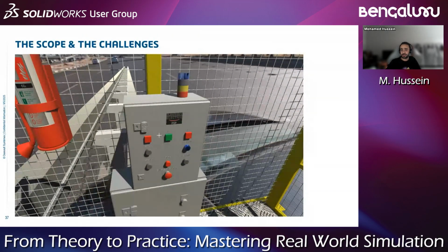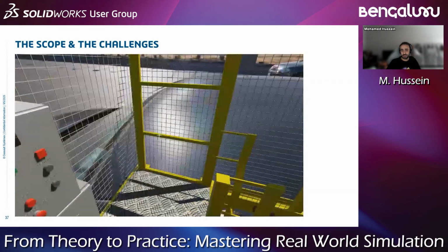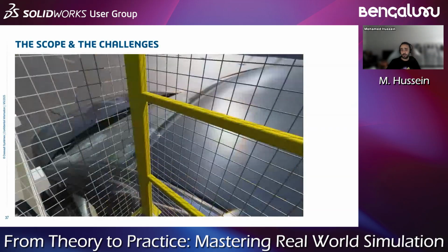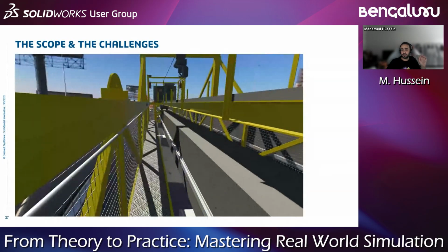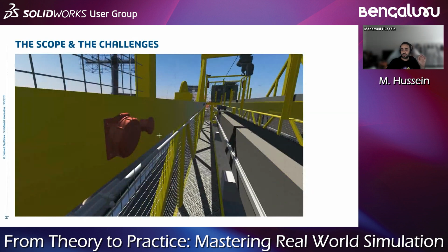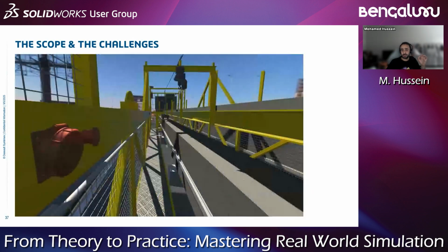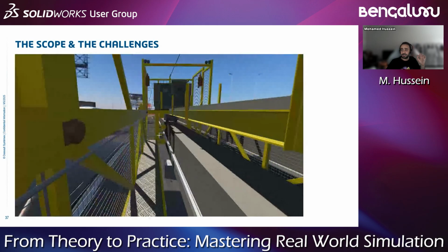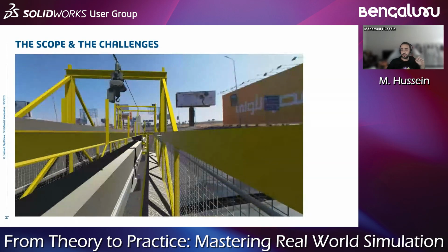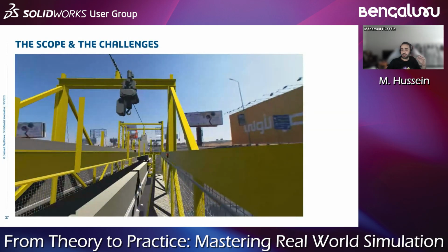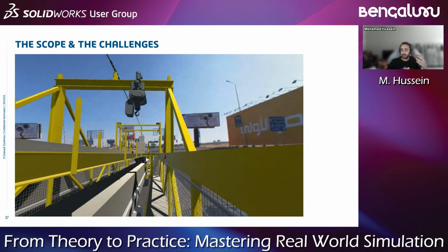The cart can move in both directions and each has a specific color on the control panel. For example, here you can see it in blue, and if I stop it and move it the other way, you can see it in green. For safety purposes, there are 6 emergency switches in different places on the cart, which can immediately stop the cart in case of any emergency. These hand brakes, which you can see right now, must all be locked to enable the worker to move the hoist and start loading and unloading the power rail from the ground.